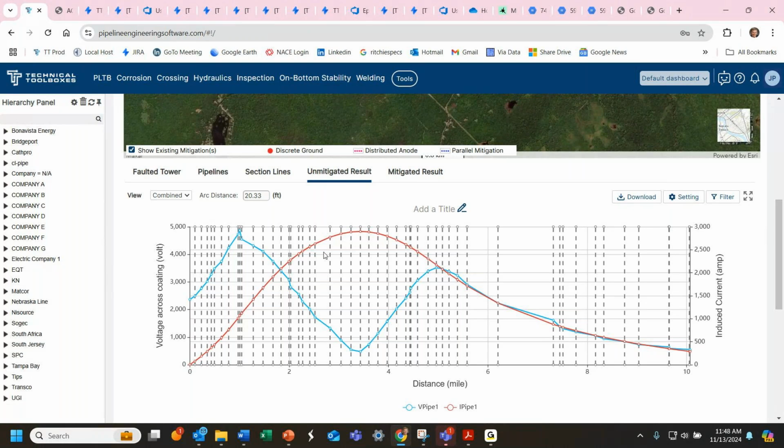We have ways to estimate the voltages on the power lines, if you can't find the information, based on the number of discs on the insulators. But we don't have a way to estimate the load factors. You have to go to the power companies and get that. We do give you some information to get you started. We have defaults in the program, and we always recommend going with the peak loads. That's the one that's most optimum for estimating what's going on.